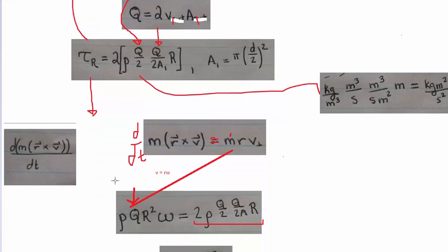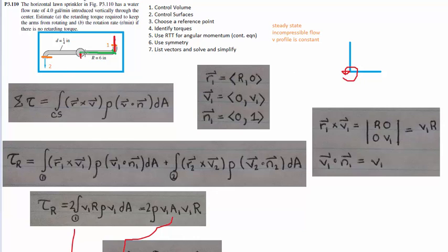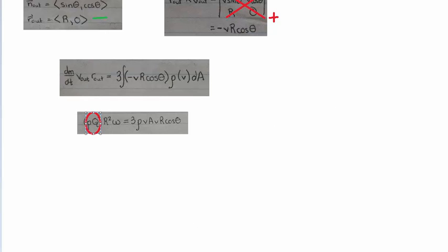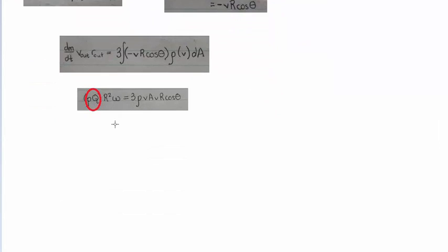Okay, but over here, when you're doing the mass flow, m dot, or mass per time, you get the total rho times Q, because the mass that's flowing out is everything that's going out through this pipe system. So this outlet and this outlet. And in this problem, that's going to be the flow going out through all 3 of these. So that's this, this, and this. So you just get rho Q, not rho Q divided by 3 or any combination of rho Q 2/3. It's going to be the entire flow going out.